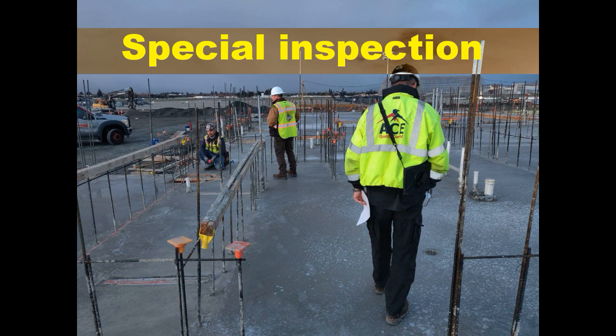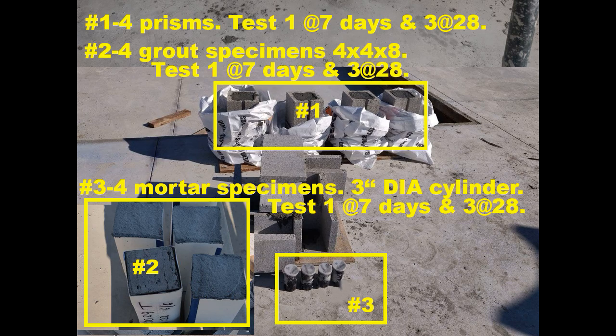Masonry inspector to verify the following are in compliance at start of construction. Compliance with approved submittals prior to start. Observe preparation of grout specimens, mortar specimens, and prisms by collecting samples and sending them to the lab for compressive strength test.